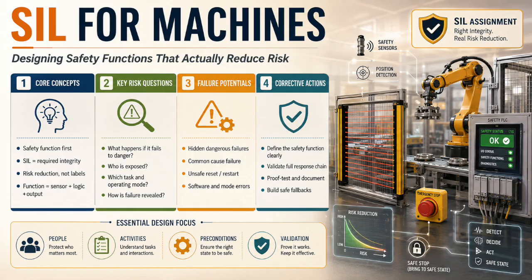Now, emergency stops deserve special attention. Emergency stops are everywhere, and they are often misunderstood. An emergency stop is not a primary safeguard. It is not a substitute for guarding. It is not a substitute for safe access design. It is not a substitute for interlocking, presence sensing, safe speed, safe torque off, or trapped key control where those are required. An emergency stop depends on recognition, reaction, reach, and timing. The person must see the danger, understand it, reach the device, press it, and the machine must stop before harm occurs. That is a lot of dependence on human response.